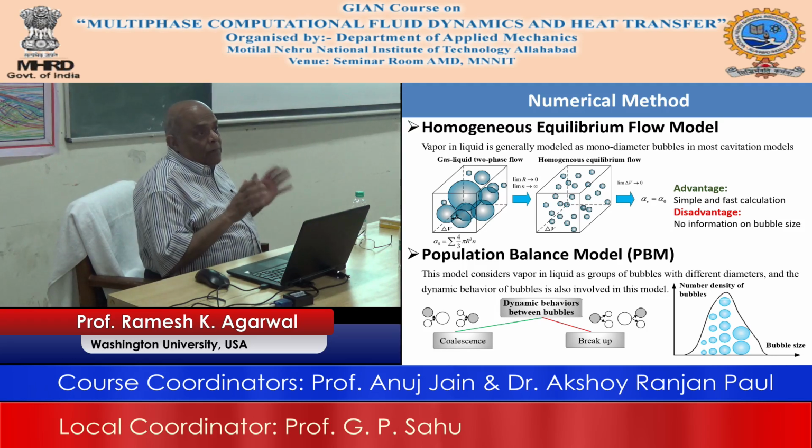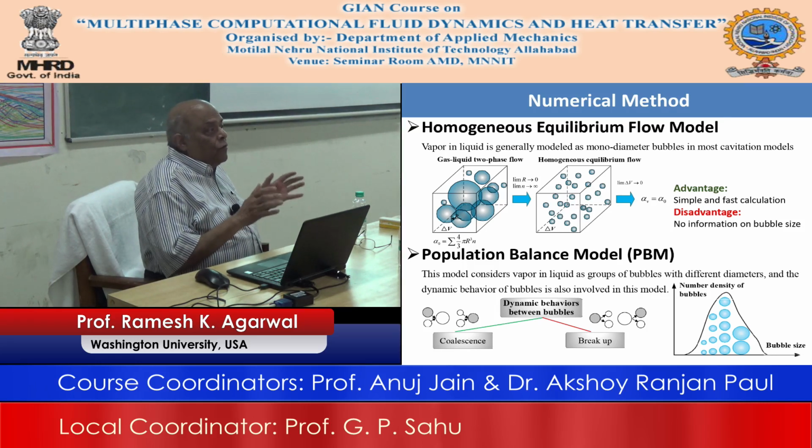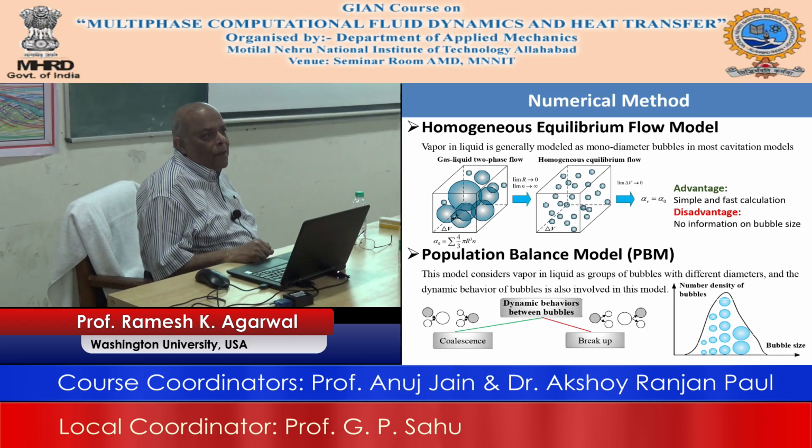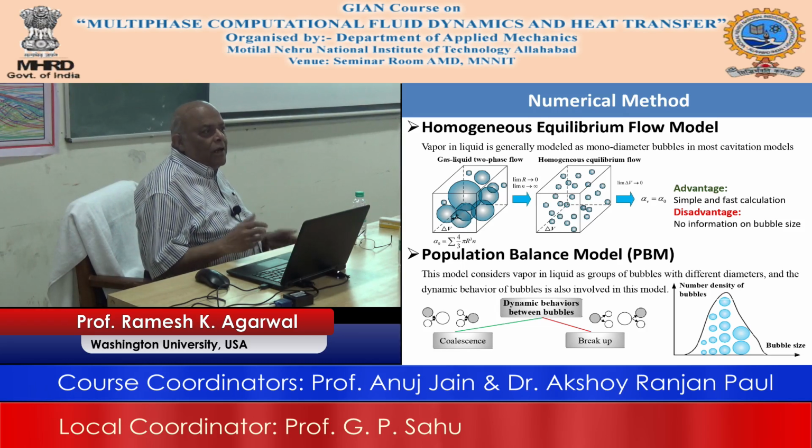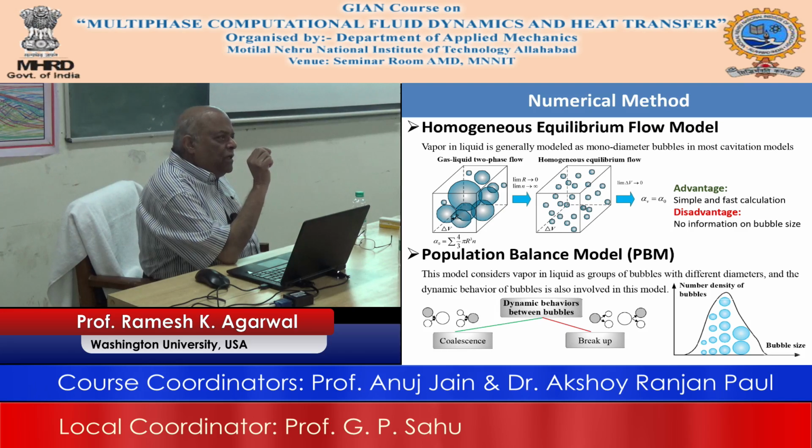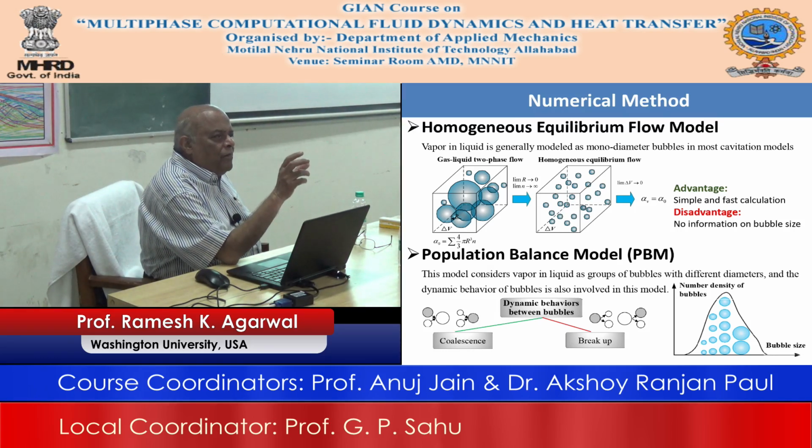So this is an academic problem in the sense that we are only going to deal with 10 bubbles. We cannot deal with 1 million bubbles, because of the scope of the problem. So the idea here is to see, if the bubbles are of different sizes and follow a Gaussian distribution, how you can solve this problem to get more information on the flow over a hydrofoil, which is our geometry, and the mean flow over the hydrofoil is calculated by ANSYS.